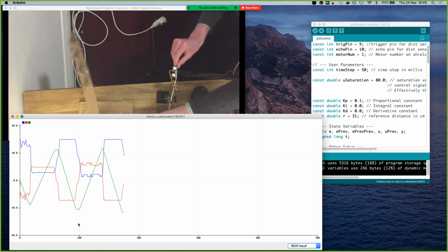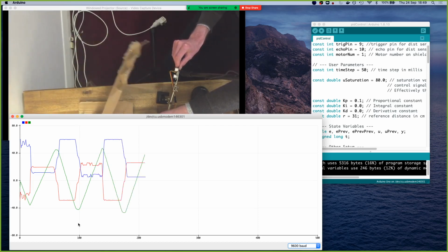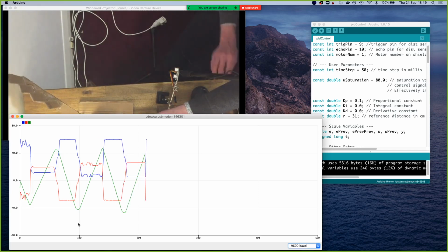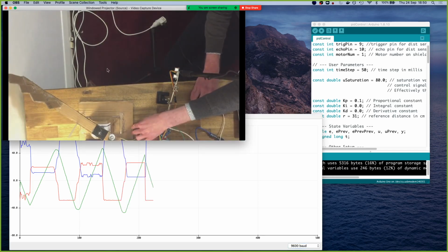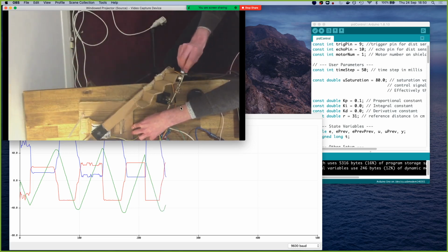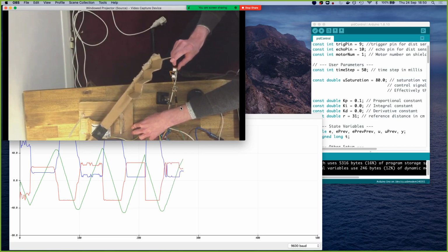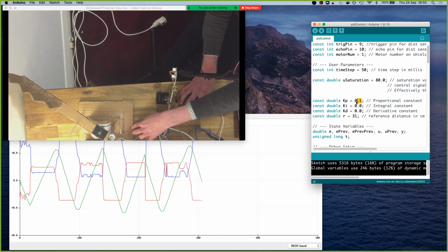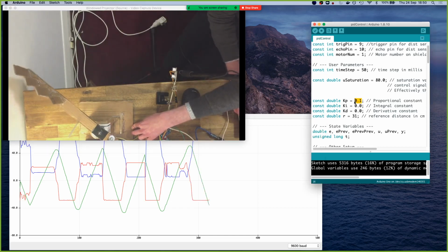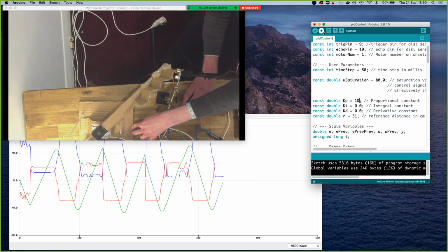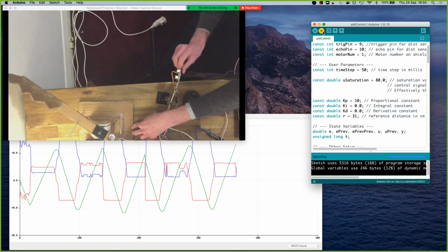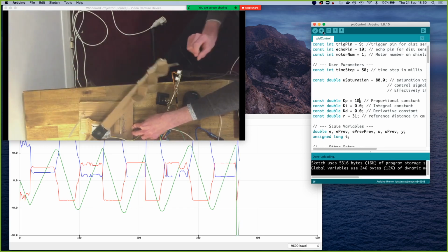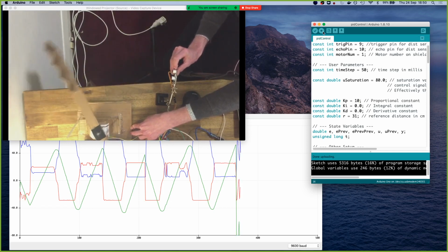We're getting this oscillating sort of idea happening, which is quite typical of a proportional gain style controller, this idea of oscillation, right? You'll see it oscillate around that equilibrium. We can change this up a bit. So if we increase the proportional gain, that means the error is going to start coming into effect quicker. So we should hopefully see, even though it's going to move faster,